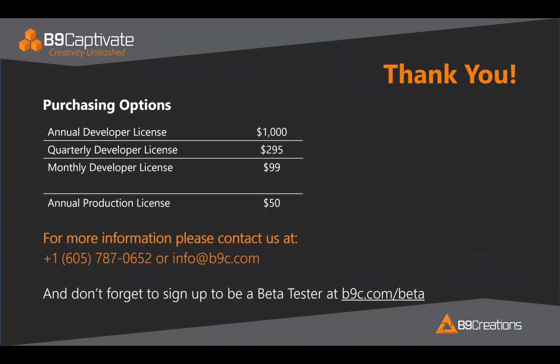And all you're trying to do with your base exposure, and I'm assuming this is normal exposure, not foundation exposure, all you're really trying to do there is make sure previous layers stick together. So a thin layer of a flat object will really get you a long way there. I would do a little sheet that's maybe 2 millimeters tall, something like that. Okay, that's good to know.